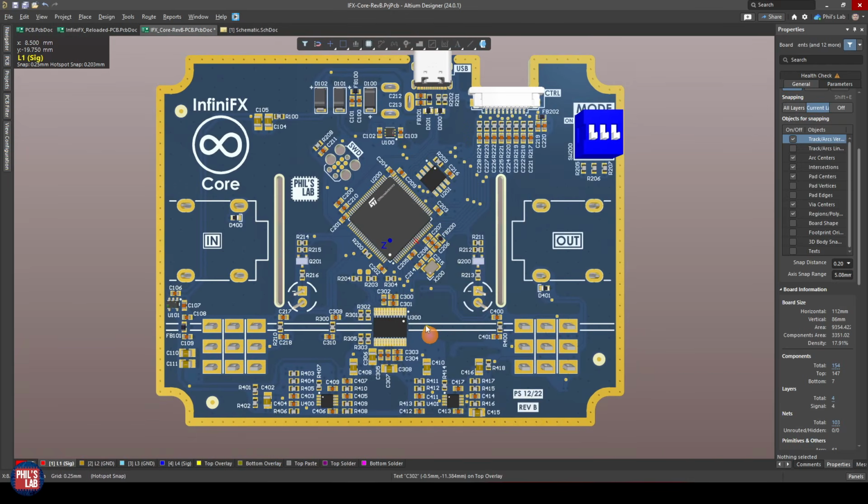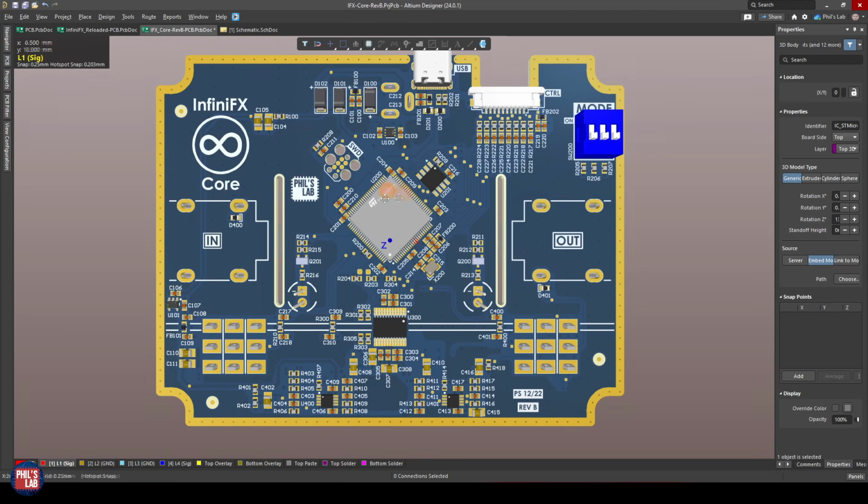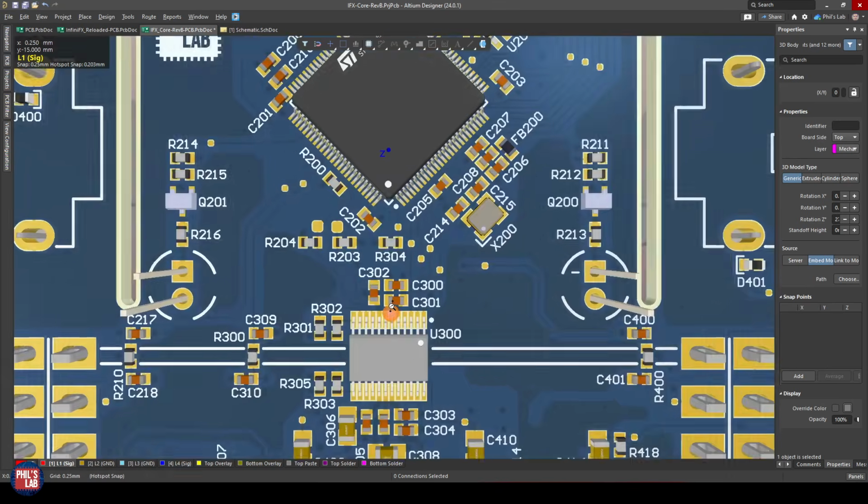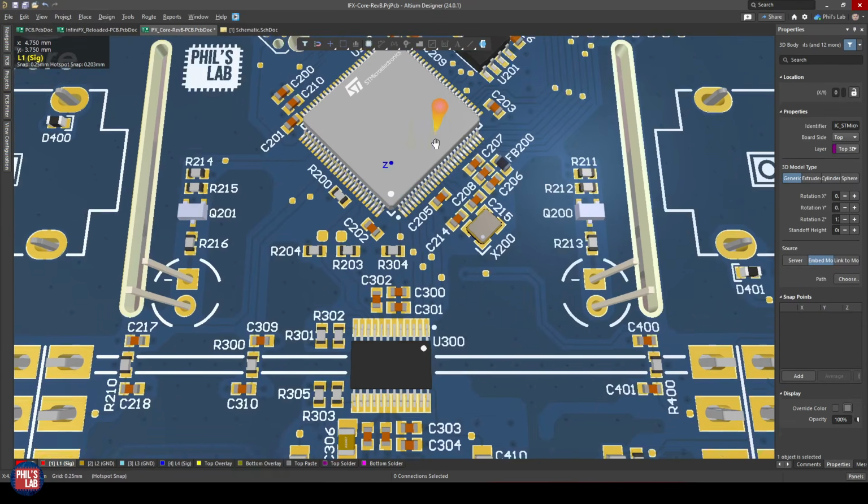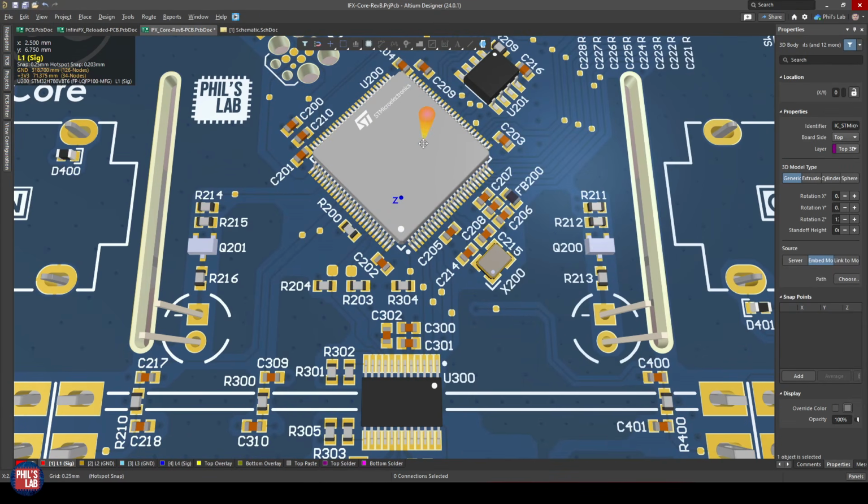So this is one that I had manufactured by PCBWay, which we saw at the start of the video. This is an audio digital signal processing board for guitar. It contains an STM32H7 microcontroller, which interfaces via I2S to this codec, and this has this analog front end, so inputs and outputs to the ADCs and DACs. But I also have to set up this codec via I2C, which is connected to, in this case, my controller, the STM32H7 microcontroller. I don't just have this fairly high bandwidth I2S interface for sound, I also have this control interface, I2C, between U200 and U300, between the microcontroller and the codec.